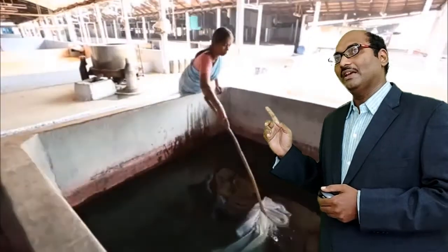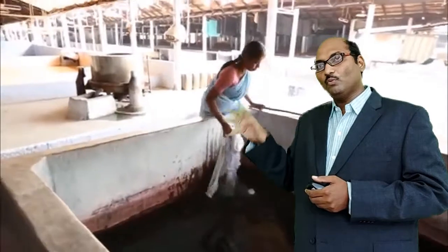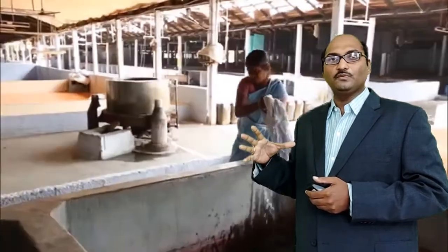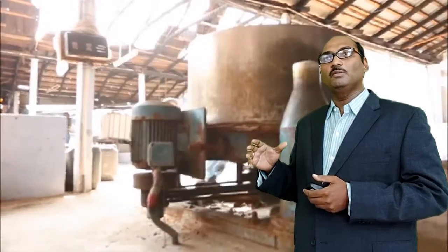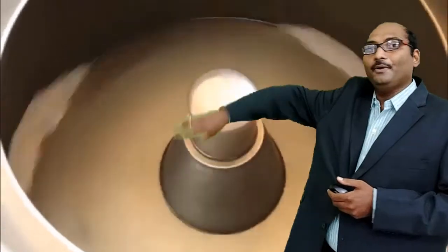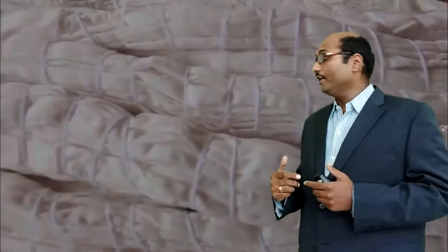So in this video, what is happening? The lady first wets the garment so that whatever air gaps are there will be gone, and the water is removed by putting it into a hydro extractor. A hydro extractor creates a centrifugal force so that the additional moisture is removed. Then, as per our pattern requirement, however we want the design, the garments are tied in that shape. When it is inserted into the dye bath, the slight moisture already there makes it easy for the dye particles to transfer to all parts of the garment.